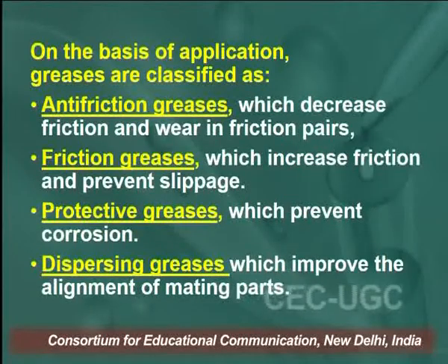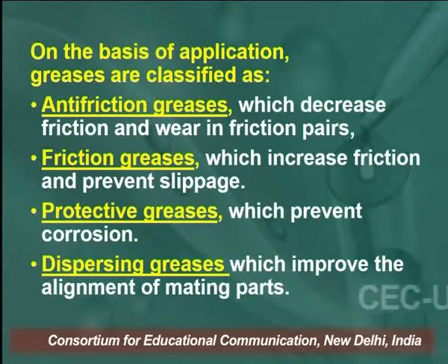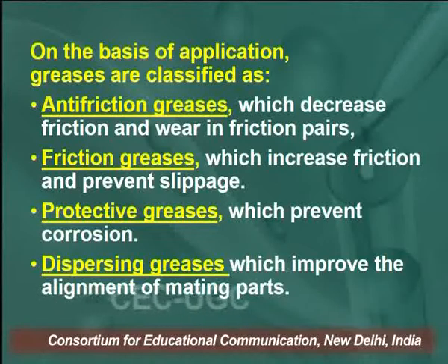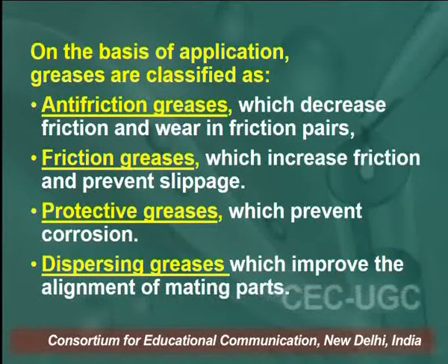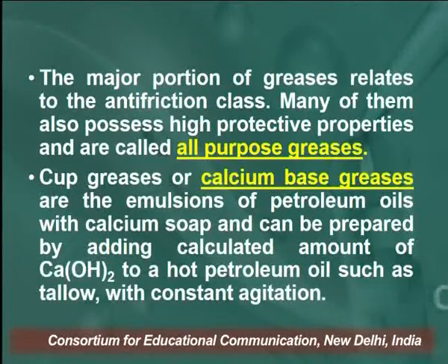On the basis of applications, greases are classified as anti-friction greases, which decrease friction and wear in friction pairs. Friction greases increase friction and prevent slippage. Protective greases prevent corrosion. Dispersing greases improve the alignment of mating parts. The major portion of greases relates to the anti-friction class. Many of them also possess high protective properties and are called all-purpose greases.